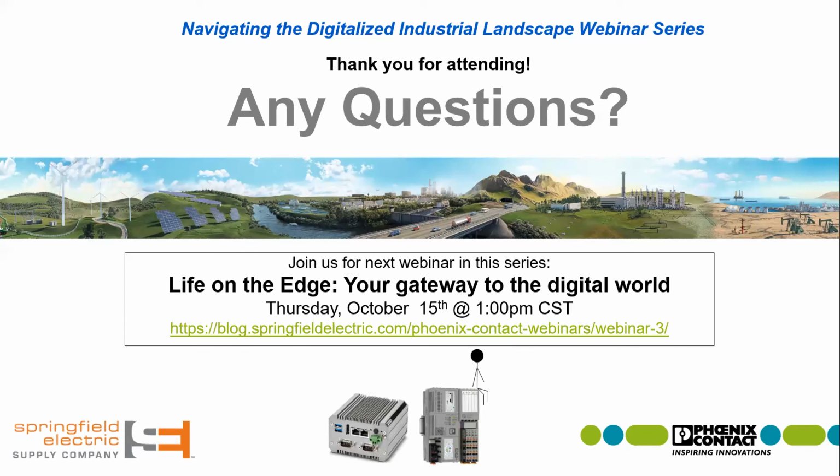We have machine builders, for example, that put the same network on every machine. They all have the same IP addresses, and then we put one of our FL MGuard security routers on the edge of that network, and we can establish a NAT rule using virtual IPs. So you can keep the machines having all the same IP addresses, but whenever you set up that VPN tunnel to it, you can use a virtual IP, a kind of fake IP, that will connect that VPN, but then the traffic will get NATed to what the real IP address is.